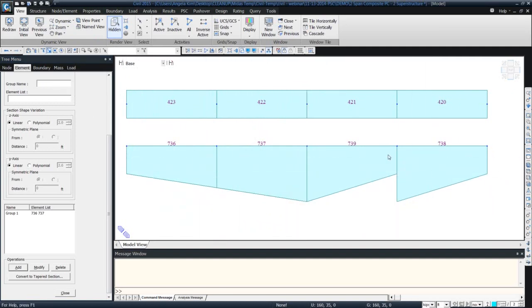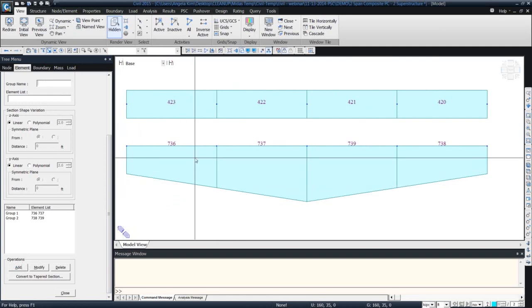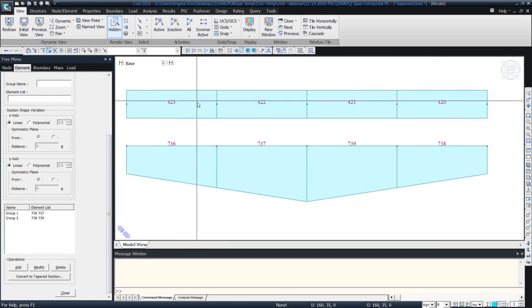I'm going to do the same for the other ends too. And as I mentioned before, for any part of the structure, is it the main beam, main girder, or is it just the deck, or just a part of a flange, or a web thickness? Any little part to the major part of the structure can be varied utilizing this taper section and taper group.